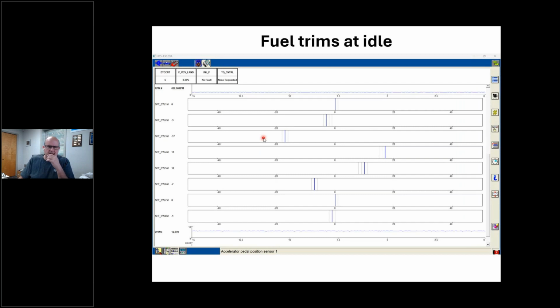It's got a cylinder 4 misfire contribution code. And I see a couple things that catch my eye. I just drew these numbers in bigger so you could see them. This is cylinders 1, 2, 3, 4, 5, 6, 7, and 8. Now remember, 4 is our guy. But I see a lot of techs look at this and they infer that I've got 3 cylinders that have trouble. And there's a reason I'm spending just a little bit of time on this.